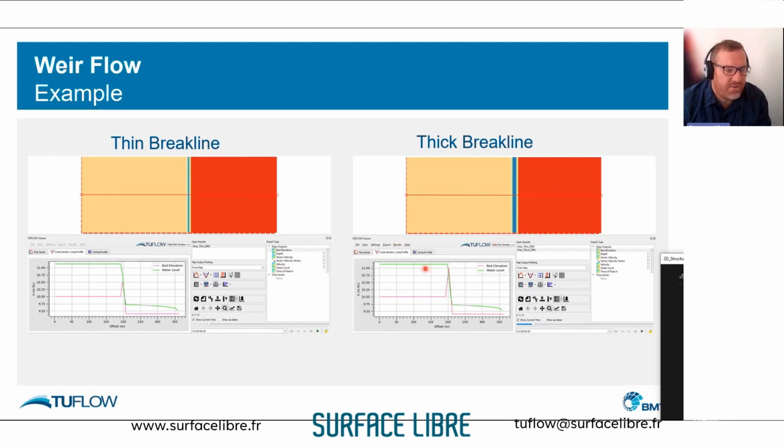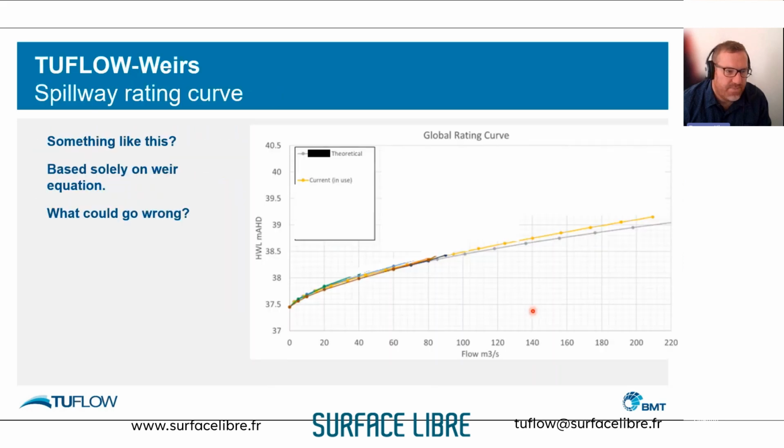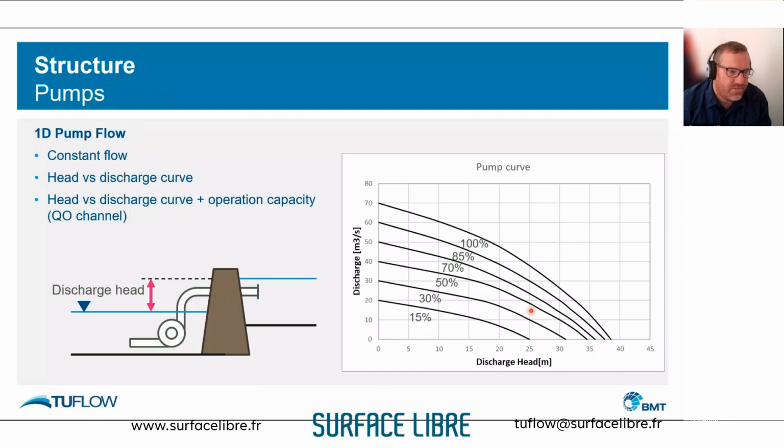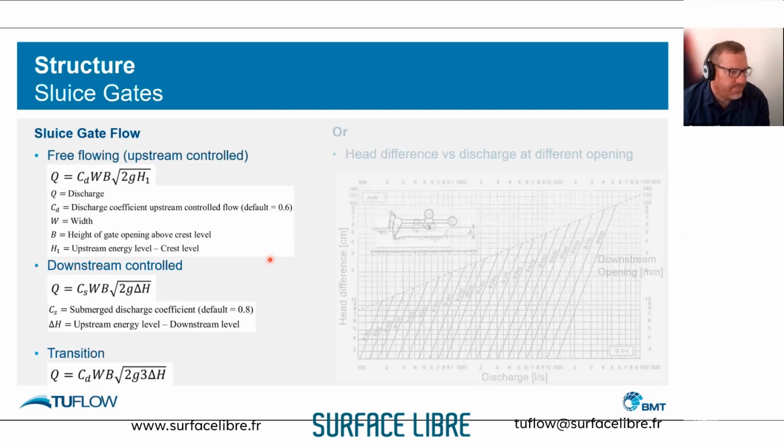The flow over the top of that uses the 2D hydrodynamics, and where it's weir flow, TUFLOW will automatically calculate that based on the advanced weir equation. Okay. And a 3D polyline will work as well? Yes. Yep. Perfect. It's doing it all on a cell face by cell face basis. Okay. Thanks.